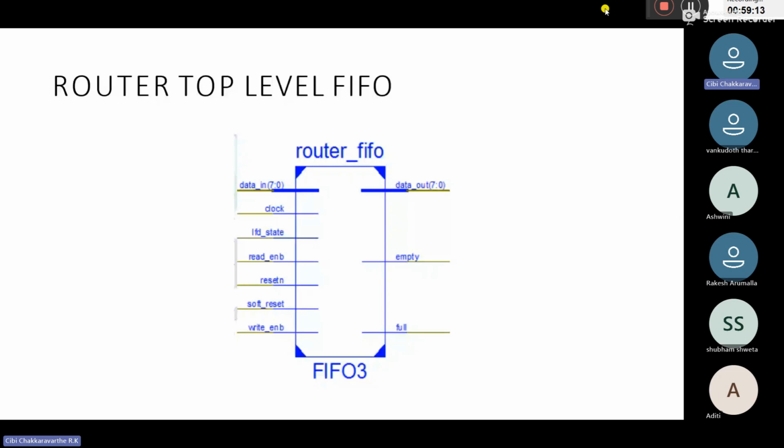It is one of the examples, one of the cases like that, but it will change for different routers. But basically what happens is it will reset, in the sense it will go to the high impedance state. High impedance state means it will not directly make all the data 0, but as of now it will be stopped. The transaction, that bus which passes the data, the packet, from one place to another place, that transaction will be completely stopped. And if we pass the soft reset, it will go to the high impedance state.